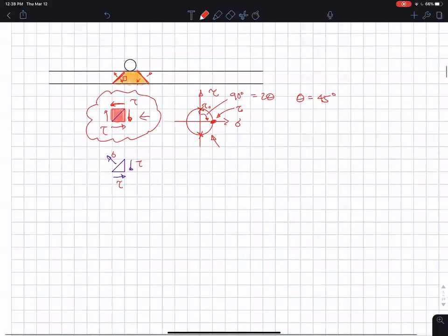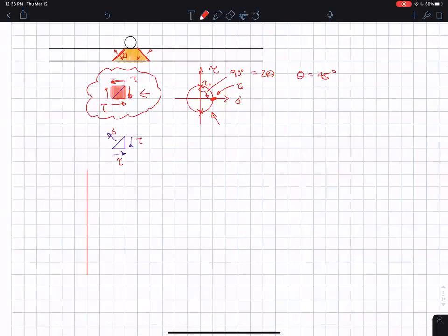And what happens in concrete, I'm going to put tension to the left, compression to the right, because concrete's so bad in tension. And when you increase the shear stress, that will happen. Every time the Mohr circle hits this envelope here, I'm going to change that color.